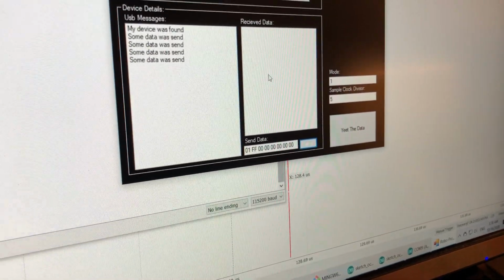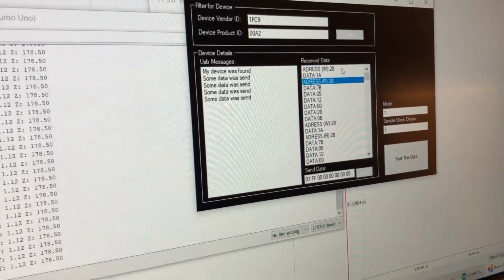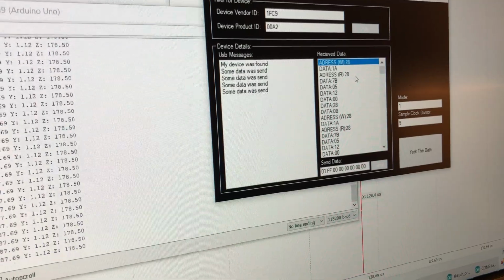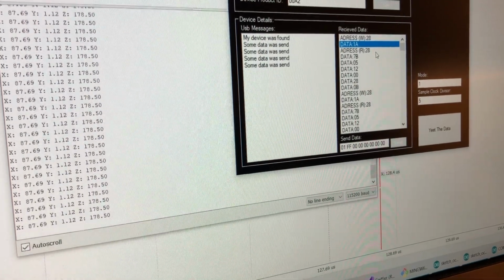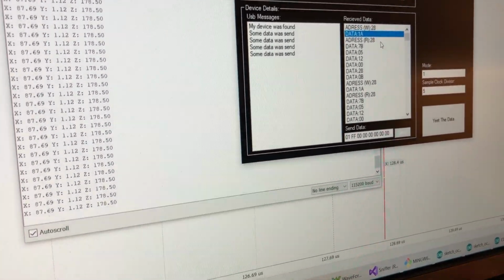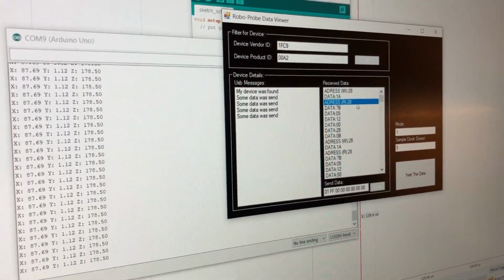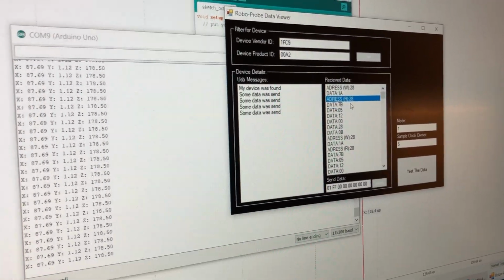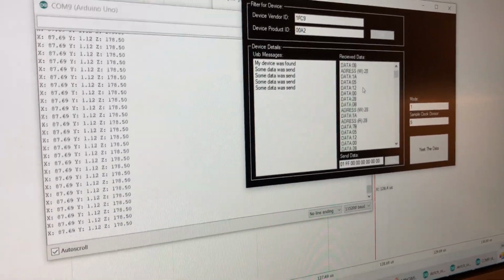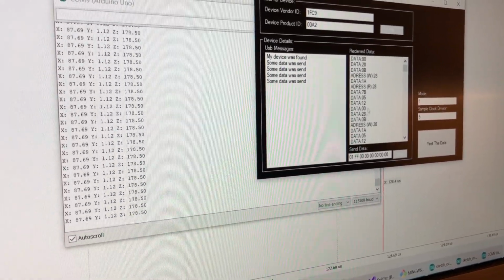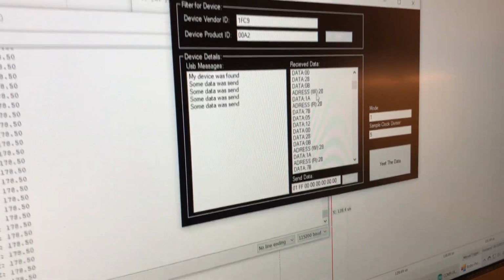I'm going to tell it to get 256 packets, and in a moment we get those 256 bytes of data, and we can see that we are writing 1A to address 28. Here we're saying, what address do we want data from on the IMU? We want data from 1A. Then we read from the IMU, whose address on the bus is 28, and we get this data back, which is our absolute orientation from the IMU. You can see this doesn't change; we have the same sequence of reads and writes as we go down through our bus history.